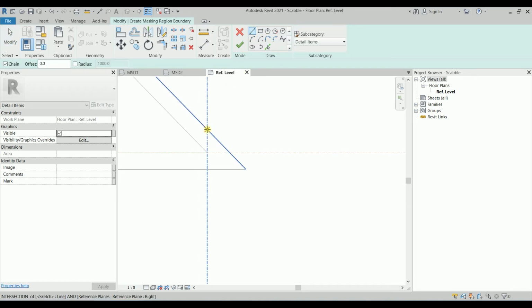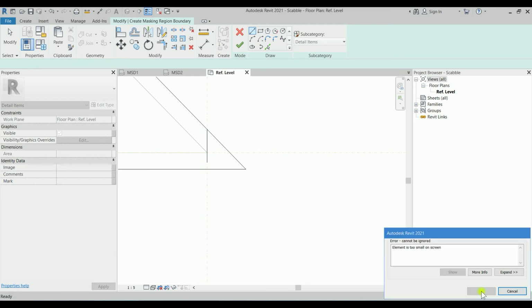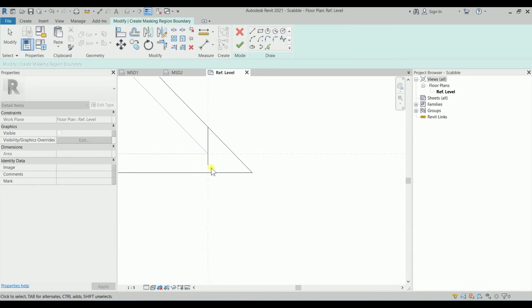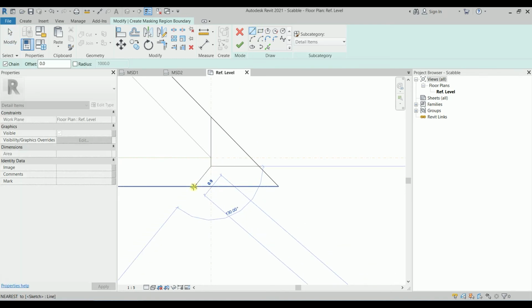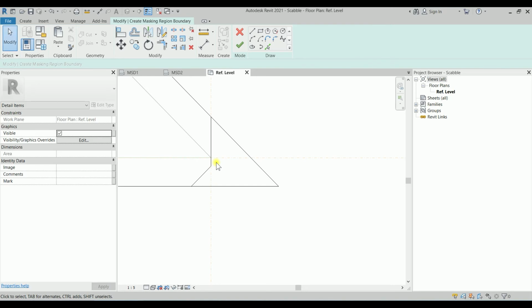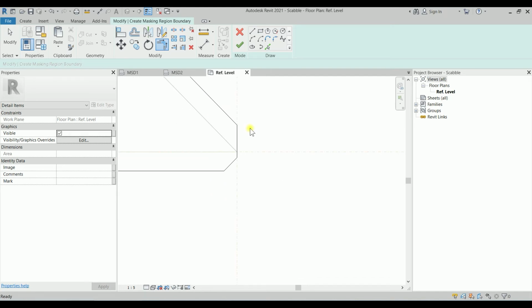I'm going to just connect these to somewhere here, and, well, that line is just too short. I'm going to create another line here. It doesn't matter how much the angle is. And then hitting Escape, typing TR for trimming, trimming here, and trimming this area. So typing AL and clicking on this line, then this line, and lock it.